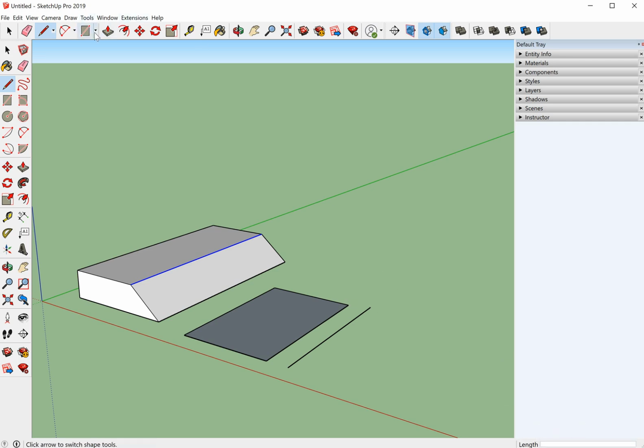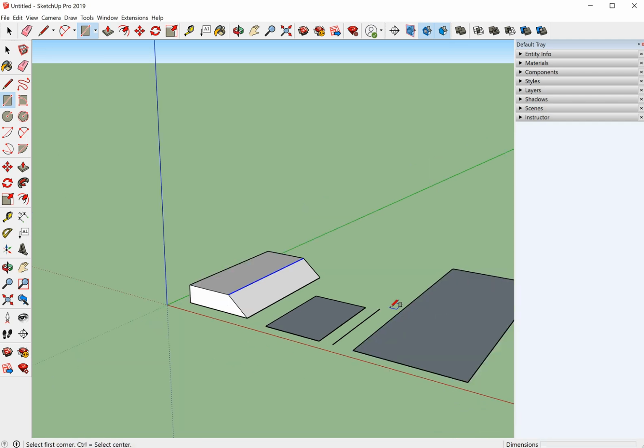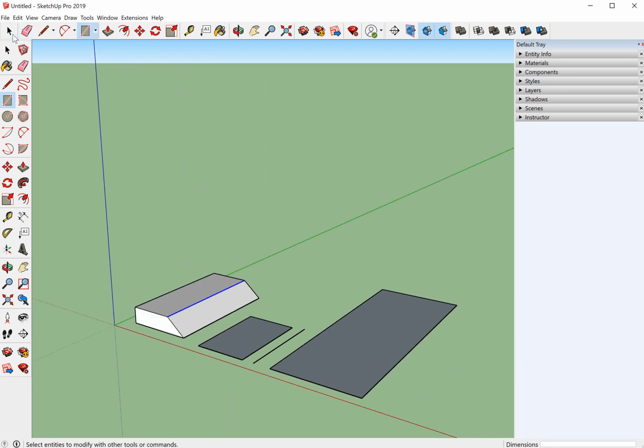You can also do the same thing with shapes. So you can do the same thing with a rectangle, but here it'll give you 2 dimensions. It'll give you the length and the width. So you can put both of those in by typing in one of the measurements first. So you can do 3 feet. And once again, it's showing up down here. So I'll do 3 feet, and then you'll want to put a comma between the 2 measurements by 8 feet, and it'll draw those dimensions out in the rectangle form for you.